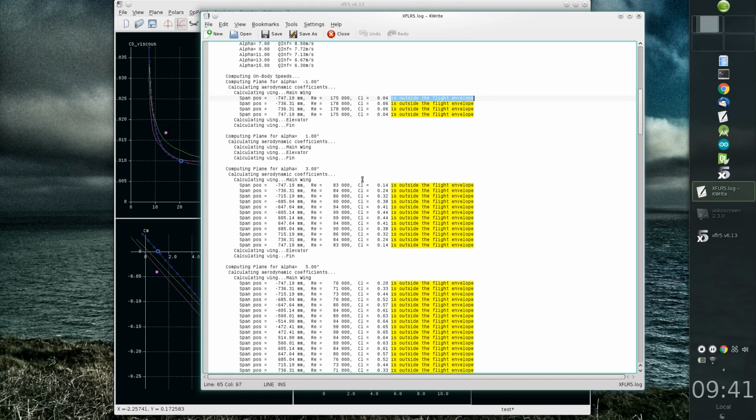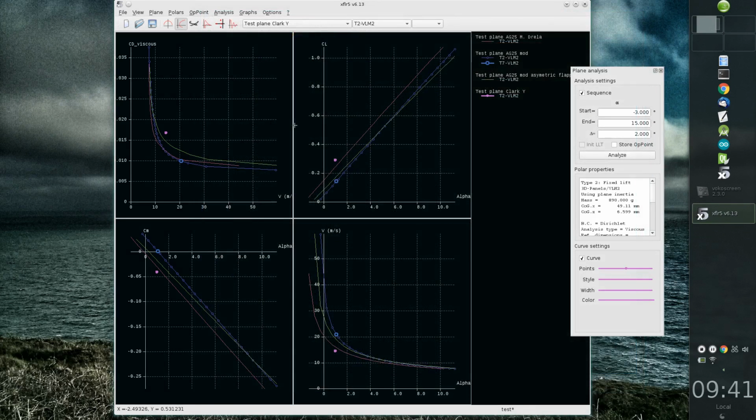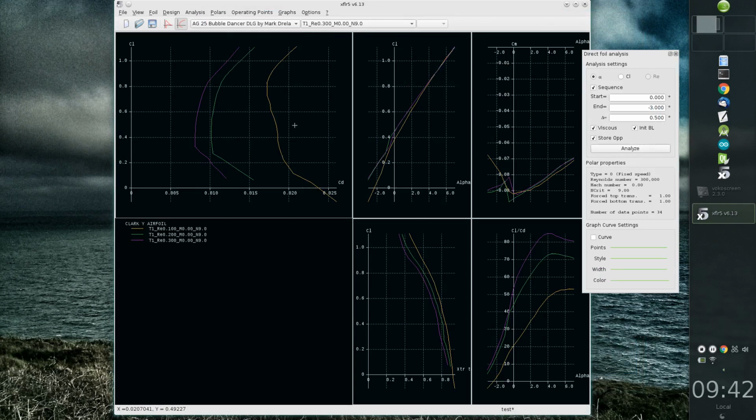To understand why this occurred, let's go back to our foil analysis and the polar mesh, and we can see that at 0.04 the curves do not extend downwards, and if they do not, the results cannot be interpolated. The viscous part cannot be deduced from this polar mesh.